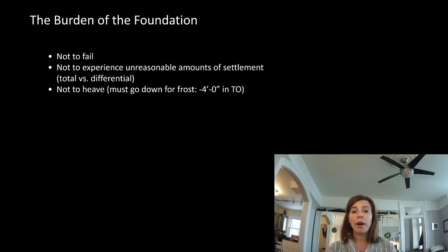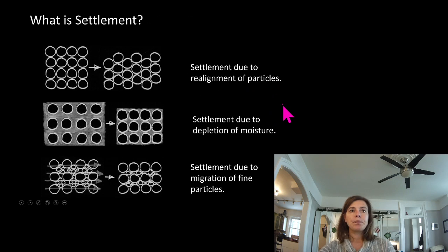In Florida, you rarely see a basement because you can just keep your structure pretty shallow within the soil grade. So locale makes a big difference for that. But frost heave is a big consideration, especially in Canada. And in southern Ontario, 4 feet is the number we worry about.